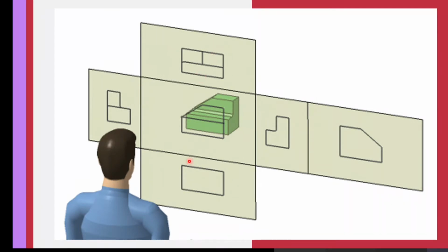You can see on a sheet of paper how we are supposed to draw all these drawings. All these should be aligned with respect to each other. This line in the front view will be aligned to the bottom view here as well as aligned to the top view here. This is the back view. The back view cannot overlap with the front view, right? We are drawing one on top, one below, one on the right side, one on the left side, and one exactly on the front view. So the last view, the back view, has to be drawn in some other plane. Usually the back view will be represented on the right side somewhere here. But the back view will be very rarely used.